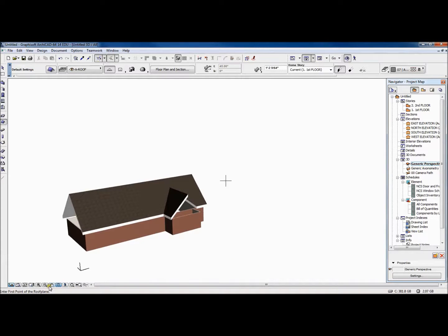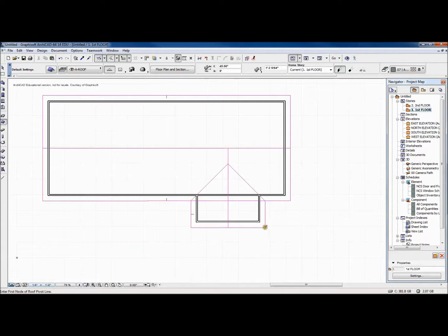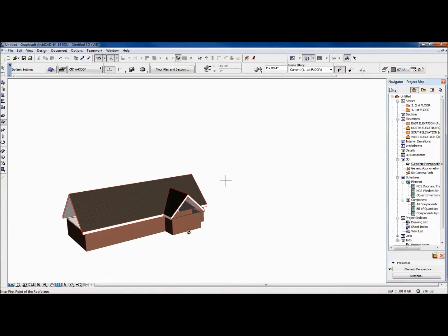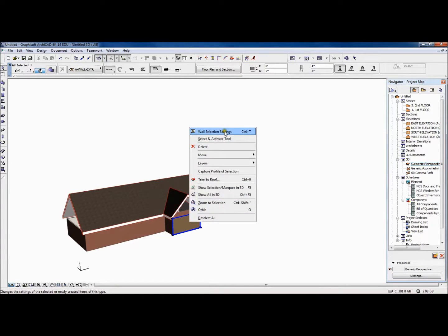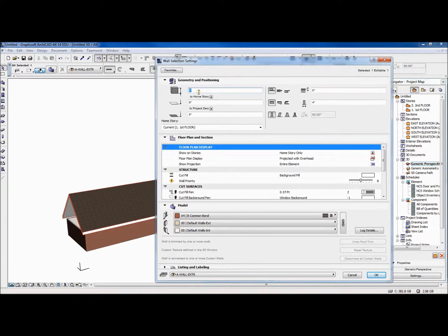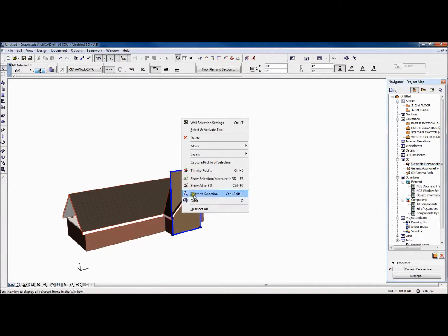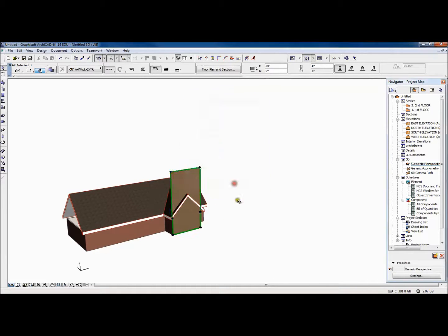And back to two-dimensional, and we will enter the pivot line, move toward the ridge, and trace the roof section that we need. And we should be done at that point, and we are. And so then you can complete the exercise by increasing the wall section to maybe 30 feet. I just like to blow on past it in terms of elevation, and then we can go ahead and trim to roof and trim.